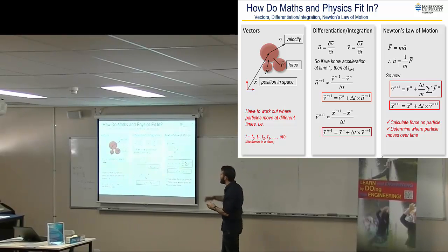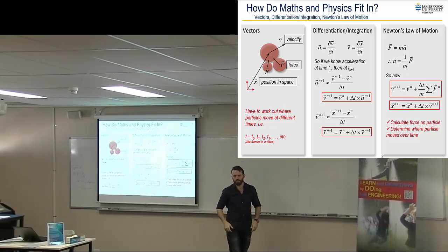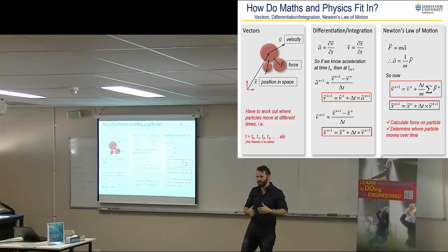Okay, so there's complicated ways of doing this, but from a very fundamental standpoint, if you're just talking about two pool balls bouncing against each other, then you can effectively have just that little bit of overlap, calculate what the force is based on a spring stiffness relationship, put that force in here, and you can calculate an update in velocity, and then the update in position where they go. So that's the maths behind one of these codes.